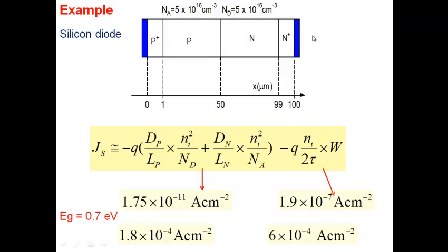Now, it turns out, if you look at lifetime of carriers in a semiconductor, it depends on the doping. Doping is like adding impurities. The more the doping in a semiconductor, the less the lifetime. Okay, so you would like lifetime to be as high as possible, which means you would like your semiconductor to be as pure as possible. So the purer the semiconductor, the less the doping in the semiconductor, the higher the lifetime. Okay, and then you get a lower reverse bias current here. What are the other means? If you were making a PN junction diode and you wanted very low reverse current, what else will you do? Try to make a very pure semiconductor with high tau. What else?